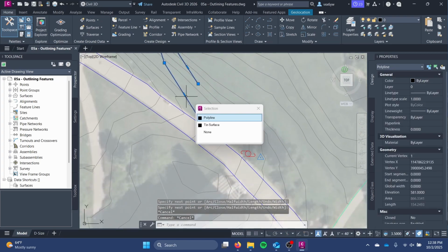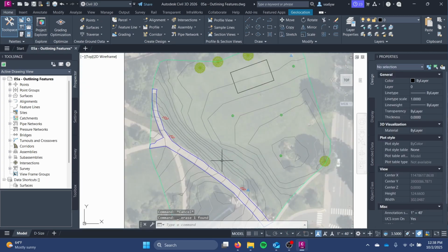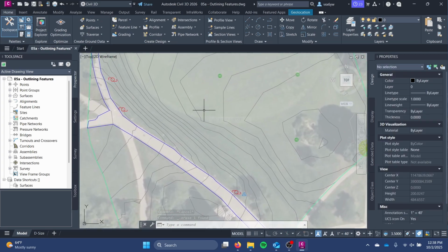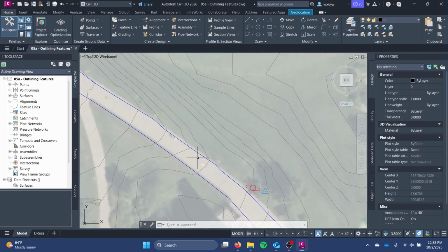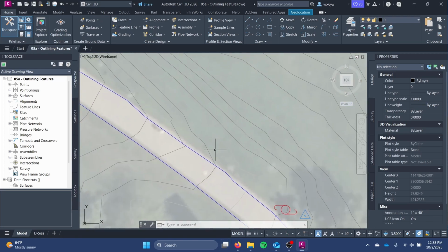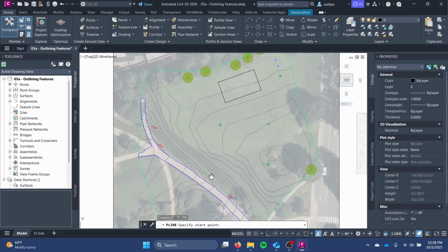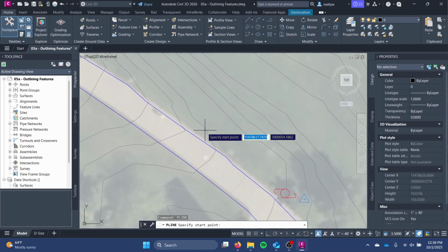So instead of doing that, I am going to make my sidewalk center line. So if I'm making my sidewalk 6 feet wide, I'm going to make the line that's 3 feet, so right in the center of it. And from there, we're going to use a different tool to offset that, and it'll make our sidewalk width automatically.